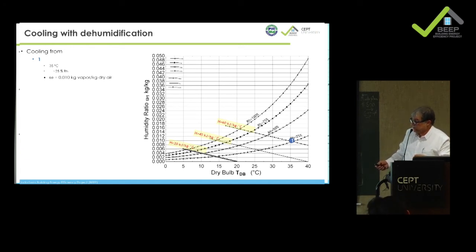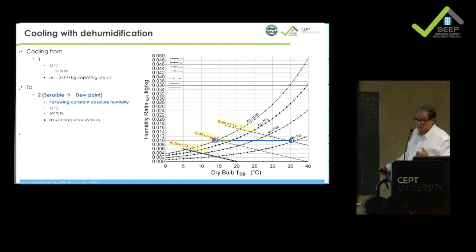So now we enter more into, you can say, the HVAC. We try to see what happens when you're cooling with dehumidification, because typically you start from air at, let's say, 35 degrees, 25% RH. It's not so much water, only about 10 grams, but nevertheless, if you go this way alone, your humidity goes up. These numbers, I'm not telling you they are the right ones. I'm showing you an example of how it works. We can discuss the real numbers that we need afterwards.